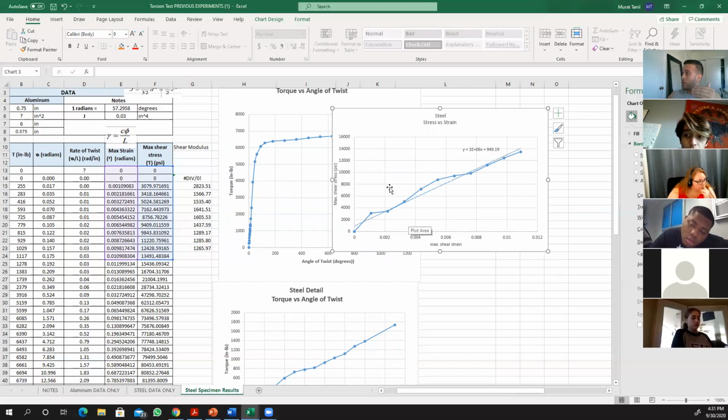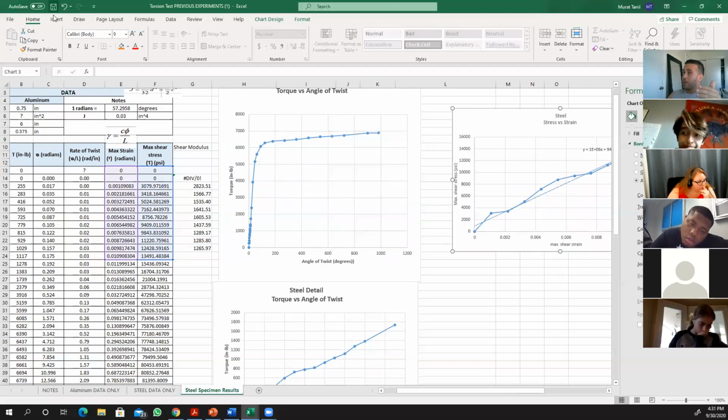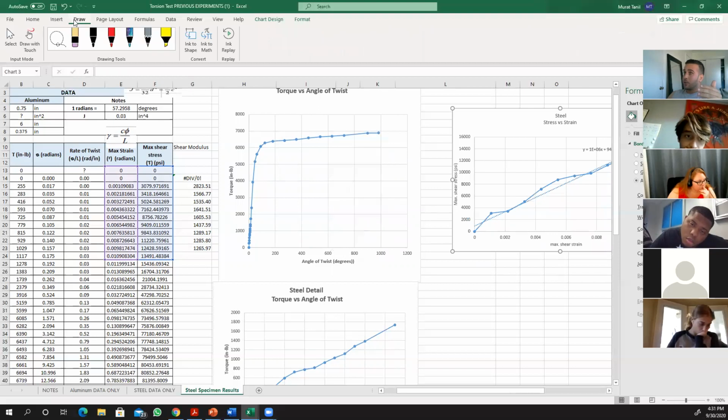Remember on tensile we used the 0.2% method where we draw a line that's parallel to the linear portion, and then we measure the corresponding tensile stress from the intersection point. That's the point that we accept as the yielding point. But on this one, it's not clear. But there is a relation.